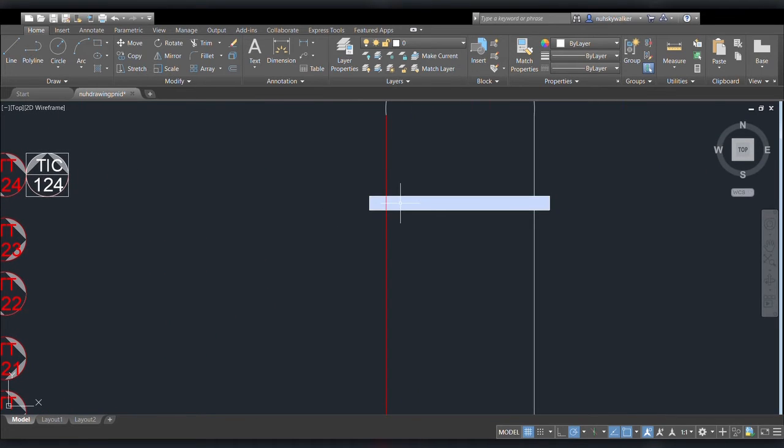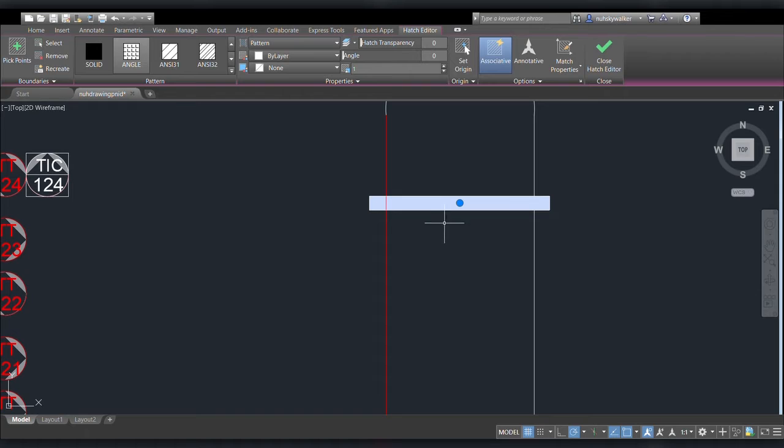So in this case, if you would like to make this part transparent, we can just use this one. I mean, hang on, yeah, you can just set the hatch transparency to approximately 50%, so that we'll be able to make it a little bit more transparent. So you just drag the transparency bar right here, just like this. Should be 50.